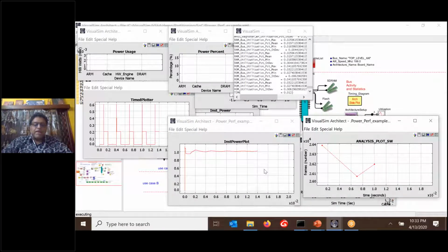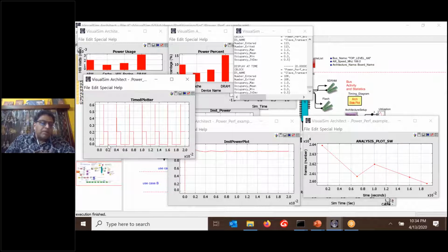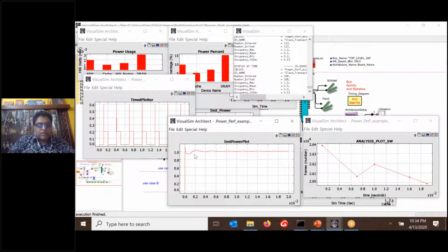So here, my performance has not dropped by a whole lot. Maybe it's about the same. But you can see now I went from 1.2 to almost hitting 1 here. There are obviously some ups and downs, and that's really because of the power management that I set up. After I'm done, I drop down to my standby state. I wait for about 1 millisecond, and then I drop down to an idle, almost a sleep state. So you can see that's exactly what this gyration conveys. And after a while, it kind of levels out. This is the average power. It levels out after a while.